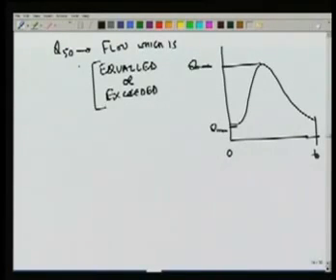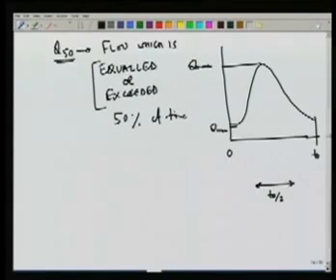So at least this amount of flow, Q50, would be available to us 50% of the time. In order to find out this Q50, we will take a line of width T0 by 2, 50%, and then we will have to shift this line up and down till this line fits exactly between the two curves, and this will give us Q50.